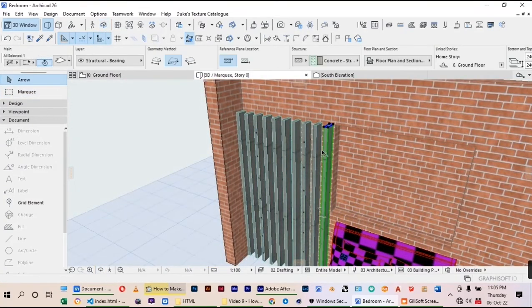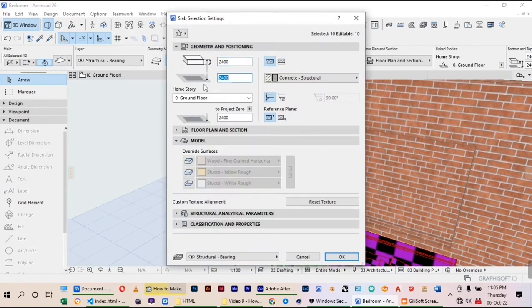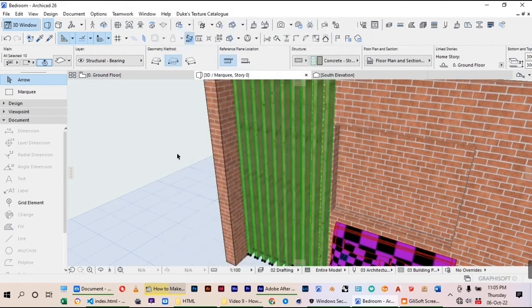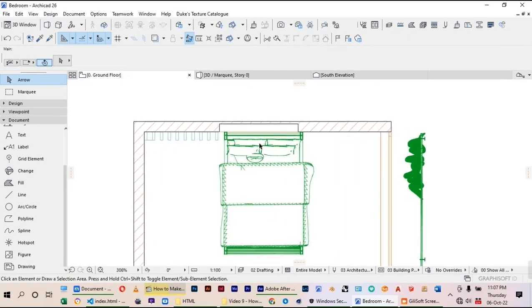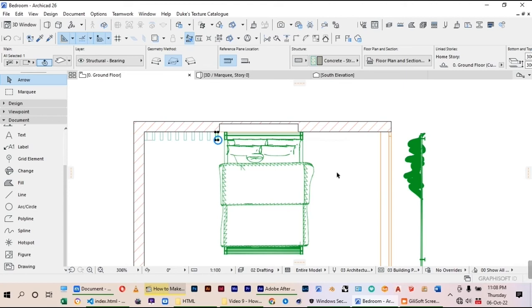The height should go all the way to the top. Settings. Let's take them to the top. That's 3 meters. And let me use for the time being wood pine. Yes, that's it. For this other side, I want also to do the struts, but again, I want this space to act as a storage area. So I want to do about 800 from the ground.